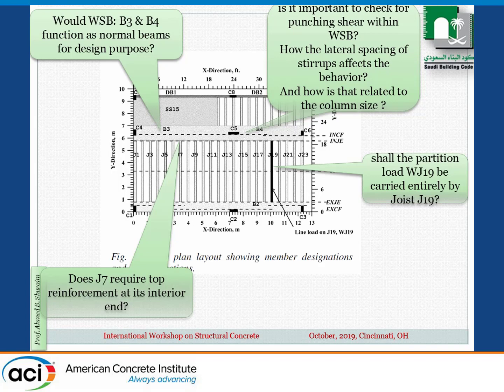The other challenge is about the partition. When you have a partition here, is this part going to be carried only by that joist, or will it be distributed? And if so, how are you going to distribute the load, and what do you need for designing? These are the source of problems for most of the construction. This is experimental, but it summarizes the challenges that we have.